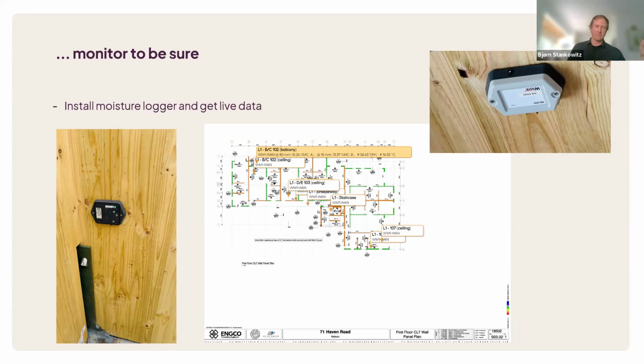And yes, there are problems and difficulties to look at it with LVL, because LVL and moisture, as you know, probably is different because of all the glue inside. So there's correction tables for that from the manufacturer, from the supplier that you would need. With these automatic live and calibrated ones, it's still a little bit difficult. So be a bit mindful around this, but talk to the supplier as well. They might give you some updates on changed settings in the future.